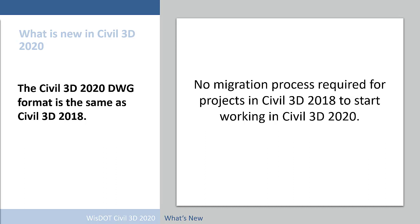This also means that X references and data shortcut drawings can be left alone in 2018 and do not need to be opened in Civil 3D 2020 or saved in Civil 3D 2020 to be read. This also goes the other way as well. If an X reference or data shortcut is saved in 2020, and if there is a need to, the drawing can be read in Civil 3D 2018.